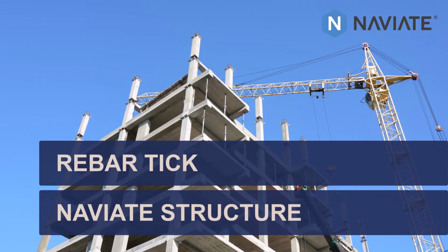In this tutorial, we will look at how Naviate Structure can help you place ticks on rebar ends. In section or elevation views, it's common practice to mark the ends of rebars with a short 30-degree oblique. We will see how to select the appropriate family, how to place the ticks, and update them when your design changes.